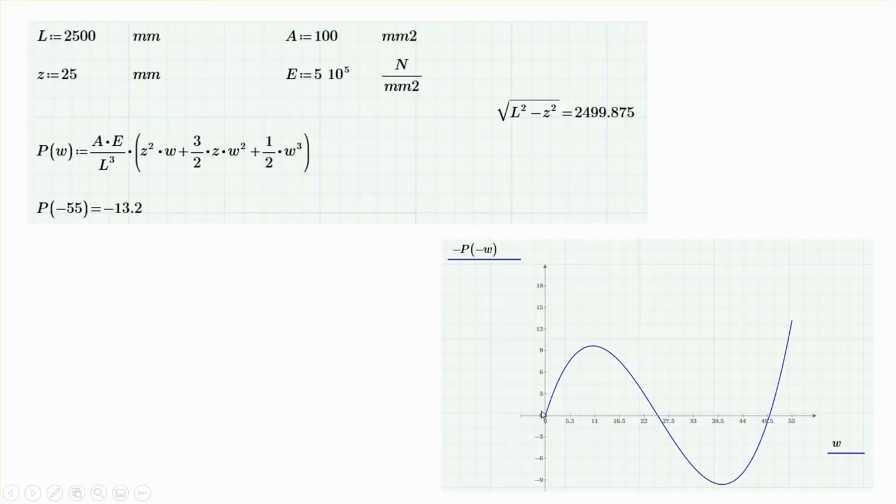So when you look at it, this is actually plotted with the same parameters. So 13.2 is roughly here. See that? Roughly here. So when I apply this with Riks step or a static step, 13.2 is roughly there, and you should go down to 55 millimeters.